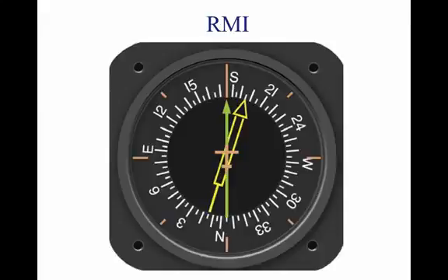During pre-flight, check the heading indicator as the gyro spools up. Make sure there are no abnormal sounds. While taxiing, the instrument should indicate turns in the correct direction, and precession should not be abnormal. At idle power settings, the gyroscopic instruments using the vacuum system might not be up to operating speeds, and precession might occur more rapidly than during flight.